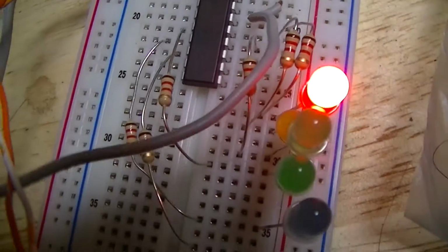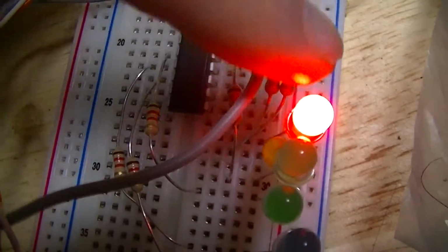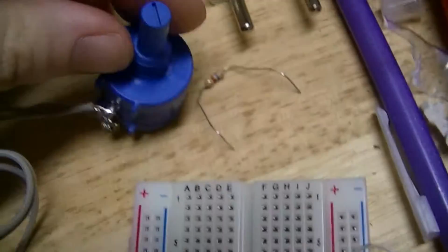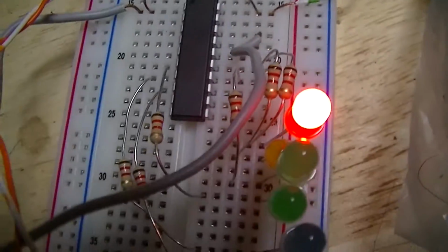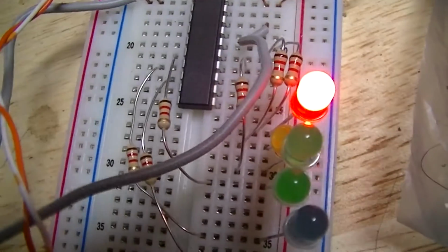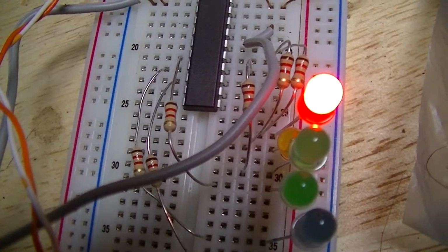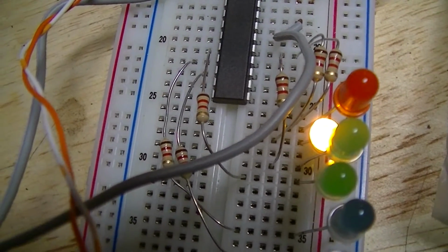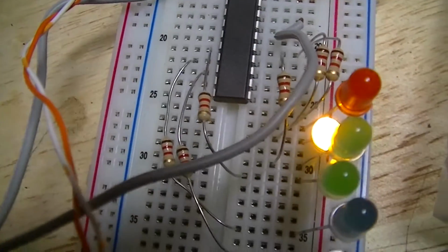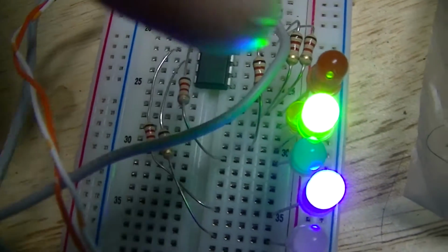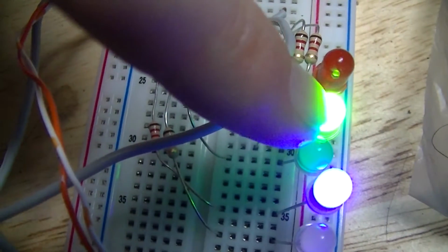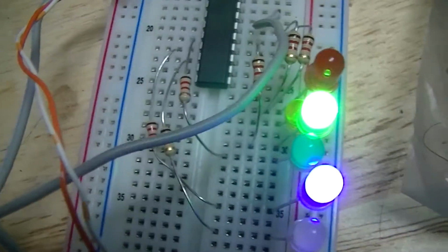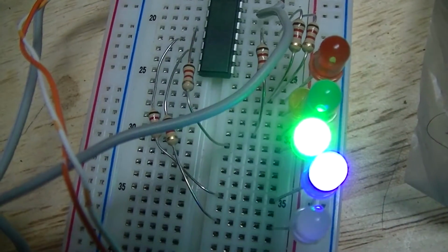The way the logic works is that if the battery is low, in this case below about 11.9 volts, right now I'm just representing it with a trim pot, only the red LED is on, then increasing up to about 12.2 volts, it turns on the yellow LED. Then when it gets up to about 12.5 volts, it turns on the first green LED and the low potential disconnect if it was already off.